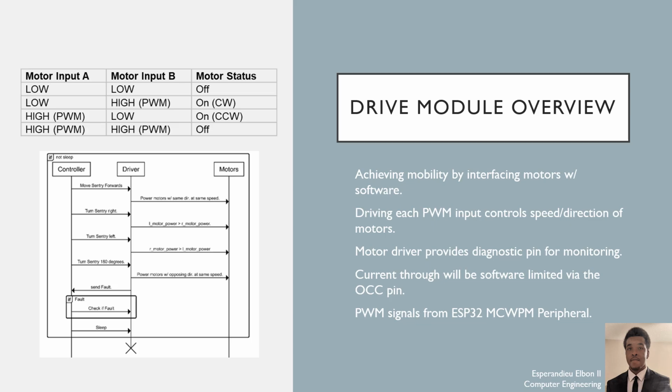In code, the motor drivers will control the motors by taking in different combinations of PWM inputs. Alternating inputs allow motors to be off, turning clockwise, or turning counterclockwise. Pairing two motors in differential drive and driving them correctly gives movements in the cardinal directions. These PWM signals are provided by dedicated channels from Espressif's Motor Control PWM API.